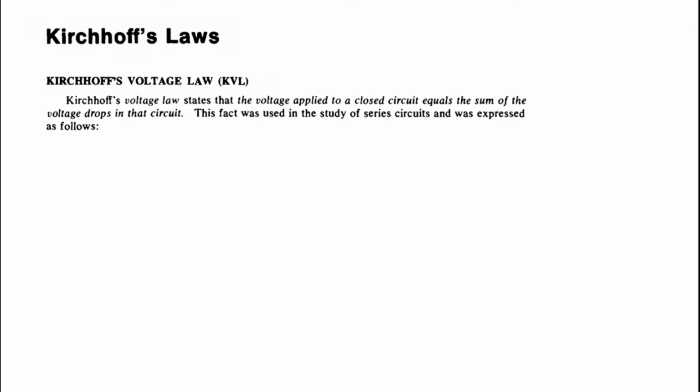For Kirchhoff's laws, we have Kirchhoff's voltage law and Kirchhoff's current law, or what we call the KVL and the KCL. Kirchhoff's voltage law, or the KVL, states that the voltage applied to a closed circuit is equal to the sum of the voltage drops in that circuit.